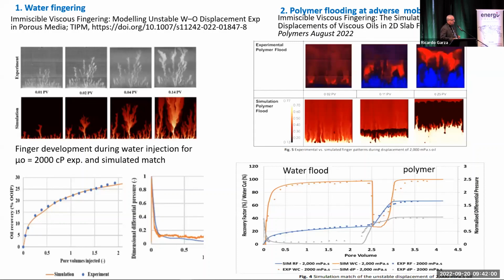And what we see on the grayscale on the top left is experiments where we have water injection at the bottom, and we see fingers growing up. It's more fractal in the beginning, and then it somewhat collapses in front. But that comes at the very late stage, especially after the breakthrough. So in this case, we had a breakthrough at 0.04 volumes.